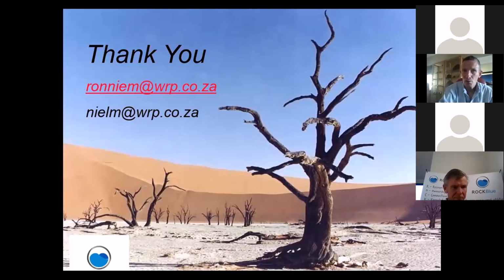Our biggest problem when it comes to pressure management is finding that the zones have been breached, either due to operation and maintenance issues, or there's been a burst pipe and they've had to connect two zones, and then after repairing it, they haven't bothered to shut them off again.